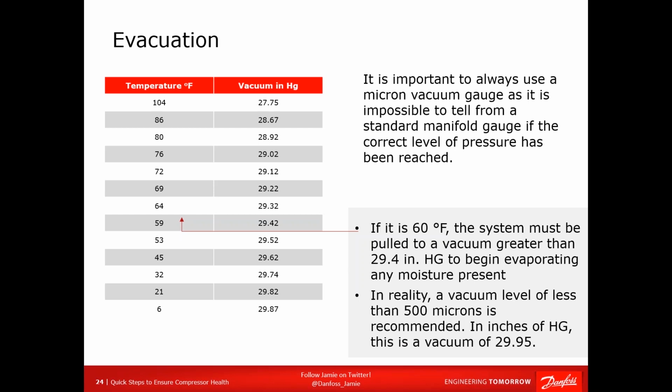Number 2, do not use manifold gauges. Leave them in the truck. There are solutions today that will save you a ton of time and will give you a very accurate evacuation. Use a micron gauge, 3/8-inch hoses. If you don't have them, get them, vacuum rated, and a core removal tool.